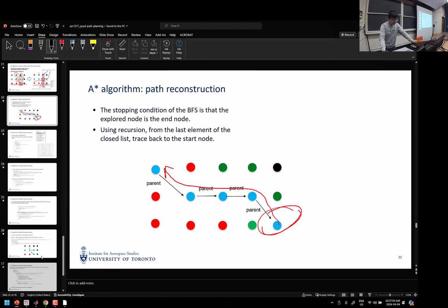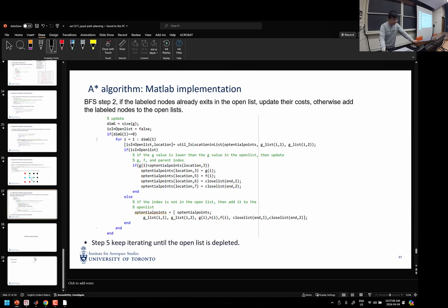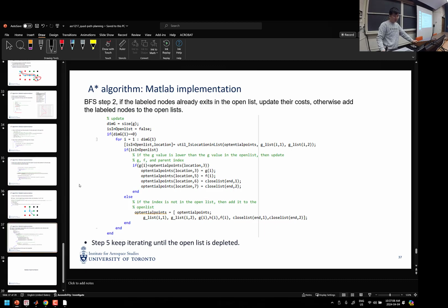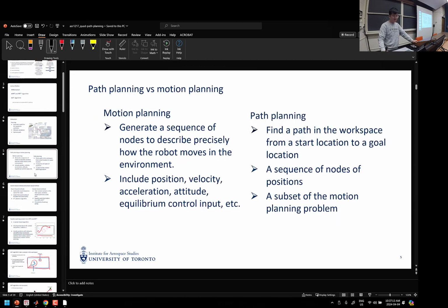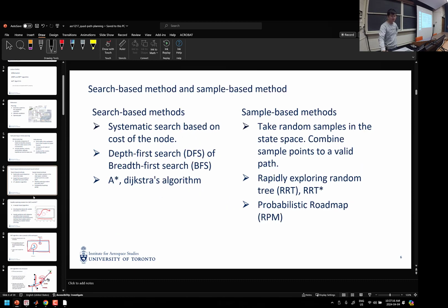Okay, so I think that's pretty much it for this lecture. I'll just do a quick recap. In this lecture I mentioned two path planning algorithms. One is RRT and its modified version RRT star. It's a sample-based algorithm, so you might need to run it multiple times to get an optimal solution, because it is only statistically better than the deterministic one.